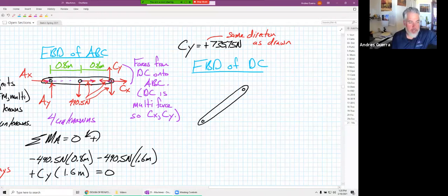So we talked last time, and it was a long, long time ago, like a week and a half ago, we talked about this. When we have this CX and CY over here on our FBD of ABC, we drew CY going up. Well, we found CY is positive, and so it is going up on this FBD. But remember, those are the forces from D to C on ABC. Over here, what direction should I draw CY? I know CY is going to be in the vertical direction. Should I draw CY up or should I draw CY down?